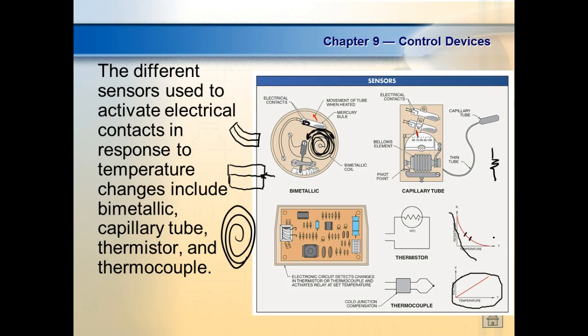Now normally what we sense is the amount of voltage, right? Because voltage we can measure across, while current we have to measure flowing through. So just about all your sensors are going to give you a voltage, right? Does that make sense? So how would I get a voltage out of a thermistor indicating a temperature?